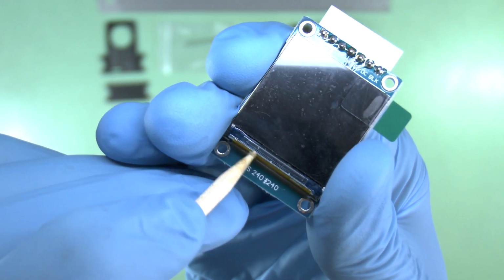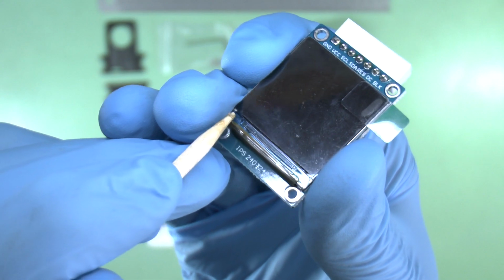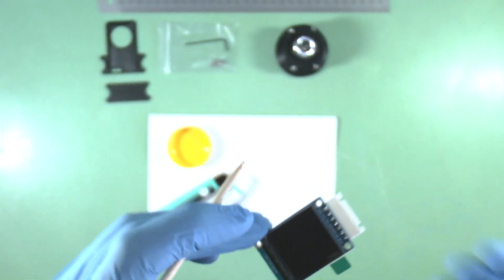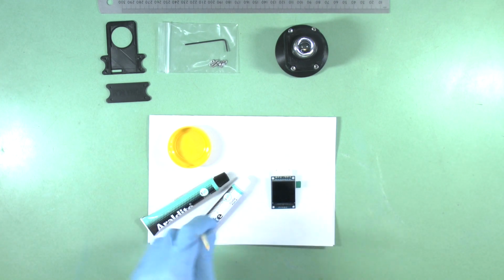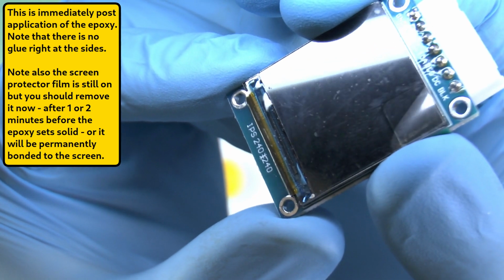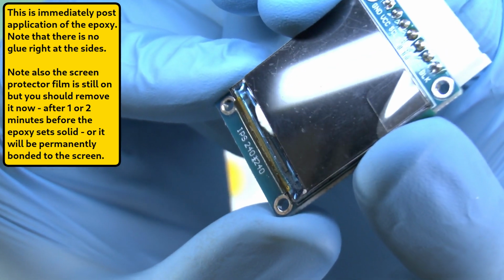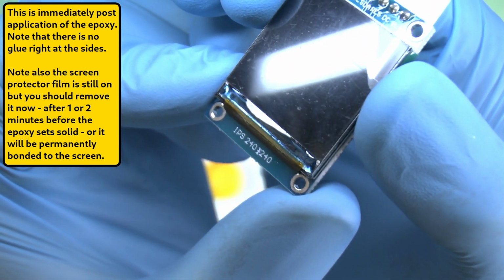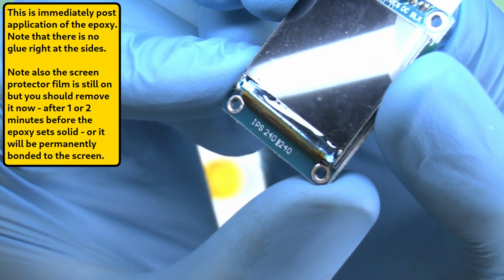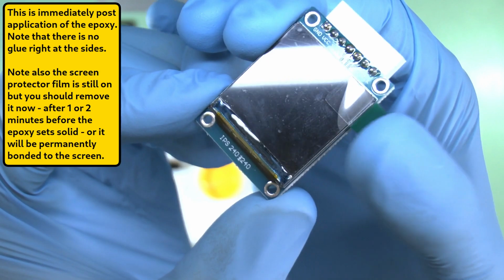The next step is to reinforce the very fragile thin glass connector strip with some strong epoxy resin and allow it to set fully before continuing. This will increase your chances of success, but it will not fully protect the thin glass from cracks, so you must still be very careful. When you do this, ensure that the epoxy does not go right to the edges to contact the metal or overflow down the sides to the underlying layers, and minimize any overspill onto the top of the screen.